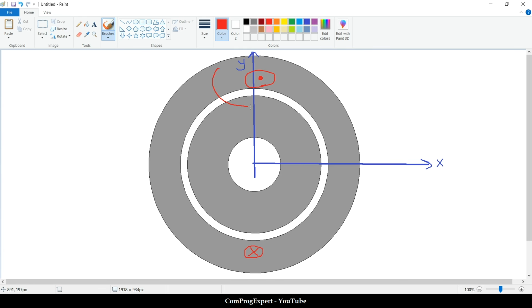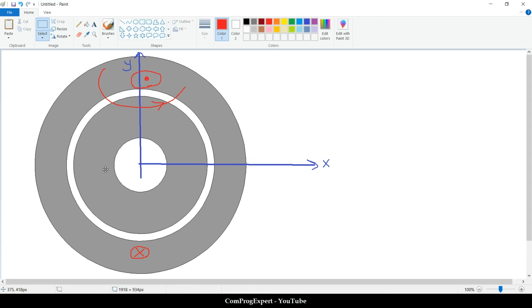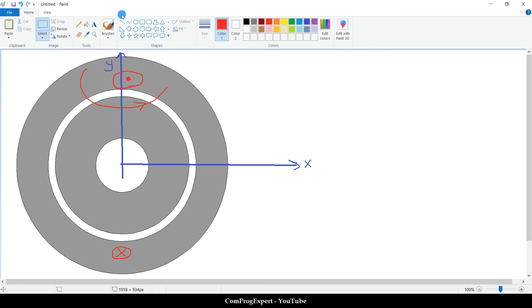This is the field generated by the phase A for a two-pole motor. In the ideal case, you can write this function B, a function of theta, equal to a peak value. This is the B1 peak value, the fundamental harmonic, times cosine of theta.